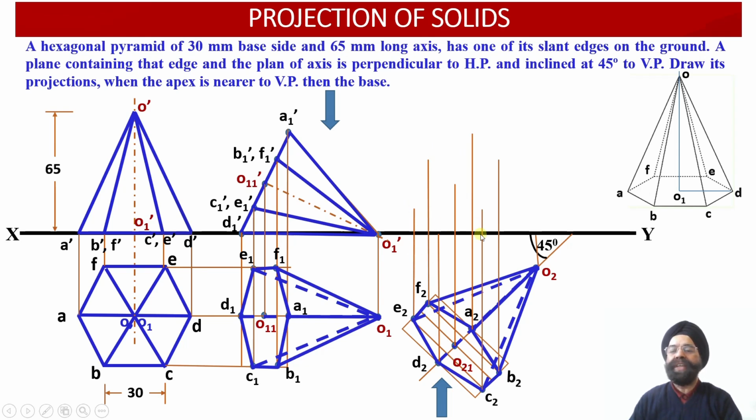the elevation projection view. We have already got the elevation projection view for the inclined hexagonal pyramid which we had obtained earlier. Now from each one of these 8 points, we are going to draw the horizontal projector lines into the elevation projection view and find out the points of intersection of the corresponding points in the elevation projection view.